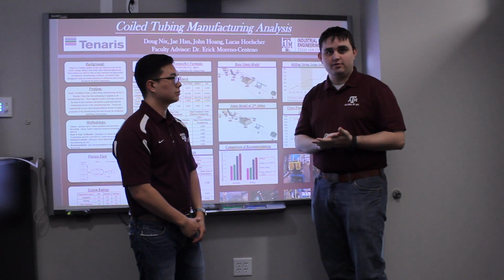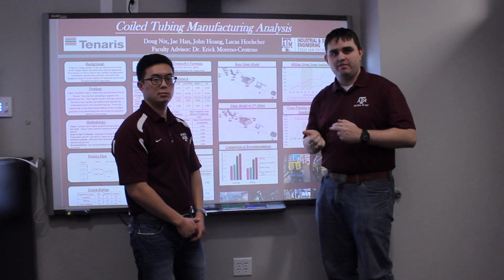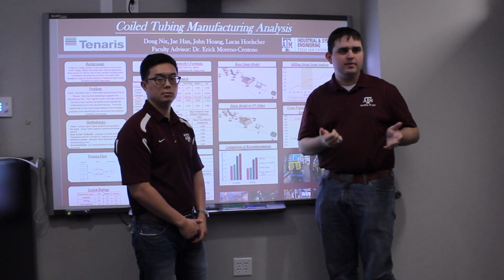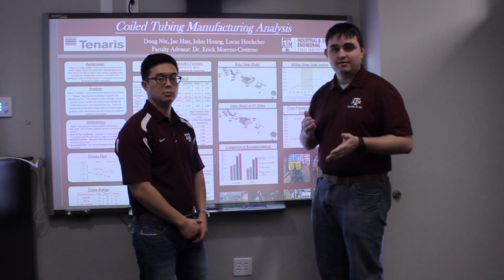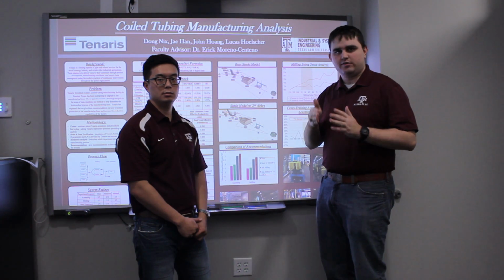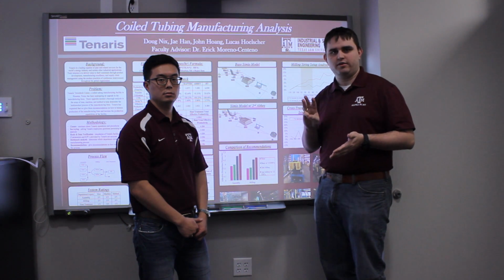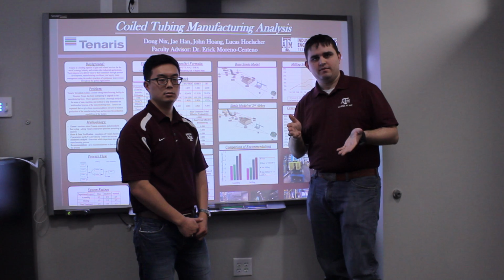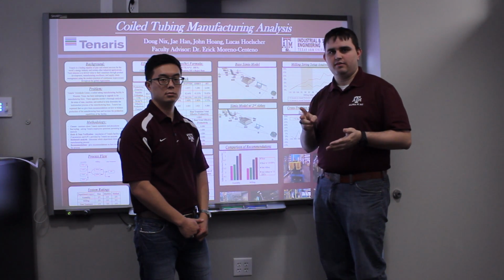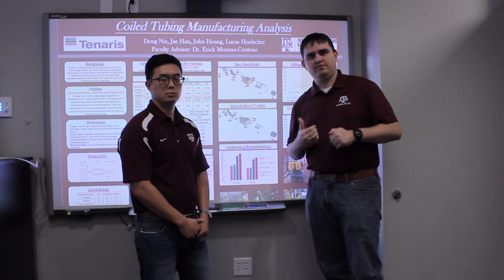During our field visits to Tenaris, we learned that in the milling setup, moving the big wheels from assembly to milling takes about 15 minutes. Now, since the hover lifts would free up 2 of the 3 workers that are ordinarily required to move a big wheel, those 2 workers can then spend the 15 minutes that they would have towards reducing mill setup.